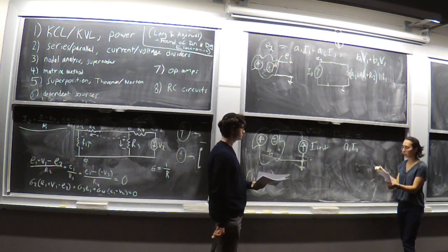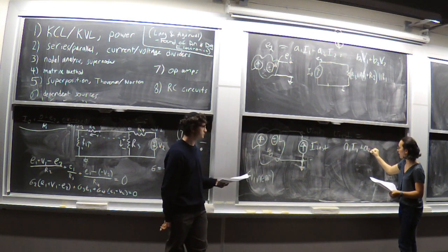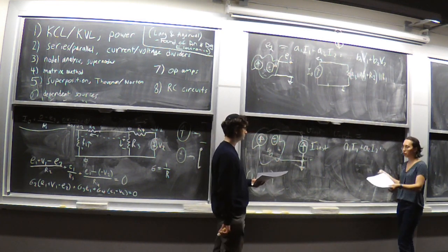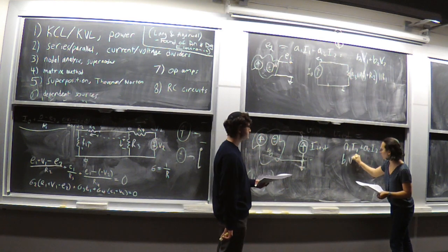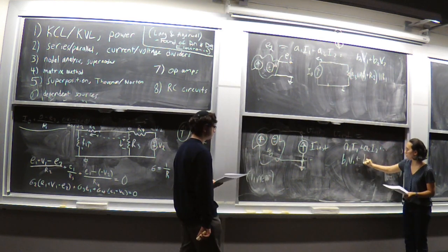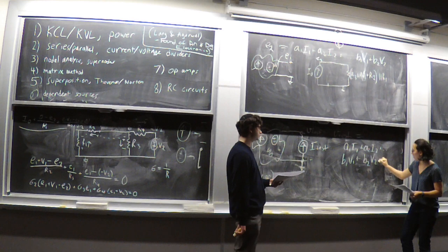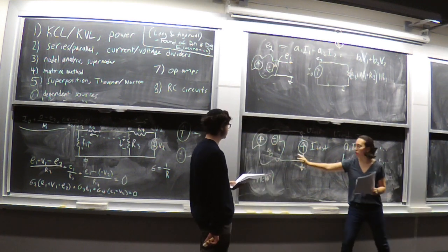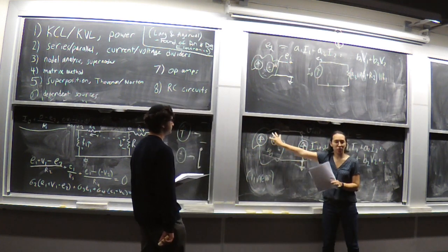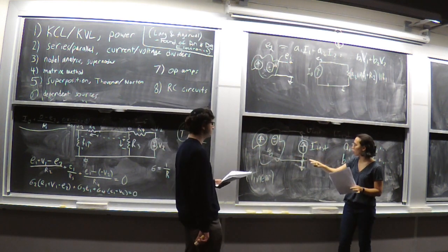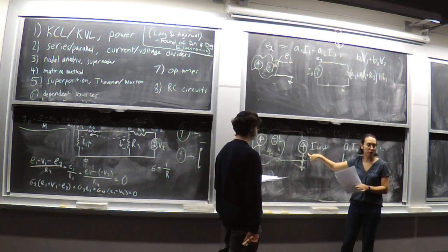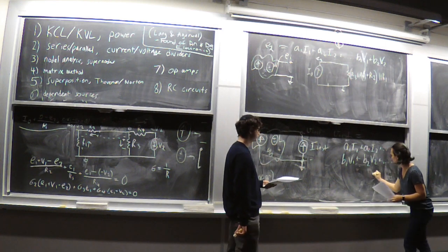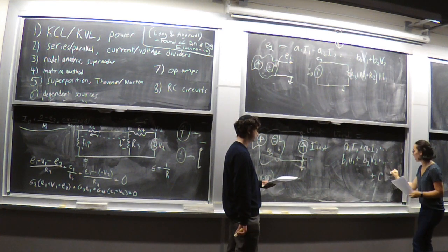It's proportional to our second current source, so A2 times I2, etc. It's proportional to our first voltage source, so B1 times V1, to our second voltage source, B2 times V2, etc. And there's one last thing that we've missed. We've now added all of the independent sources that are in here. There's one more thing, which is the current that's out here. This is the test source we're giving our circuit. So there's one more thing, and that is some constant C times I test.